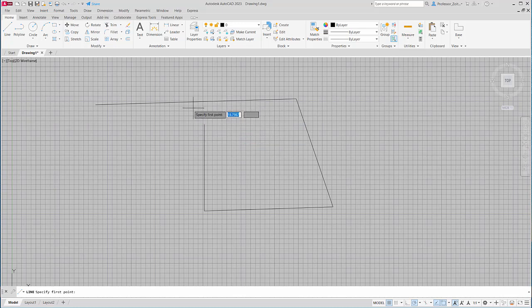And what happens is as I approach that line, it automatically shows the exact end of the line. And you can see the word endpoint. So if I'm in this position and I click with my left mouse key, it automatically finds that end. And that's one of the tools within CAD to allow us for a highly precise type of drawing, which is what we want to do as accurate as possible.